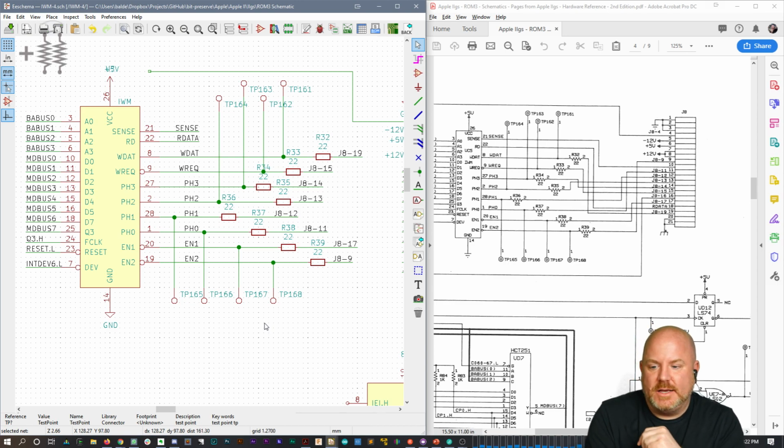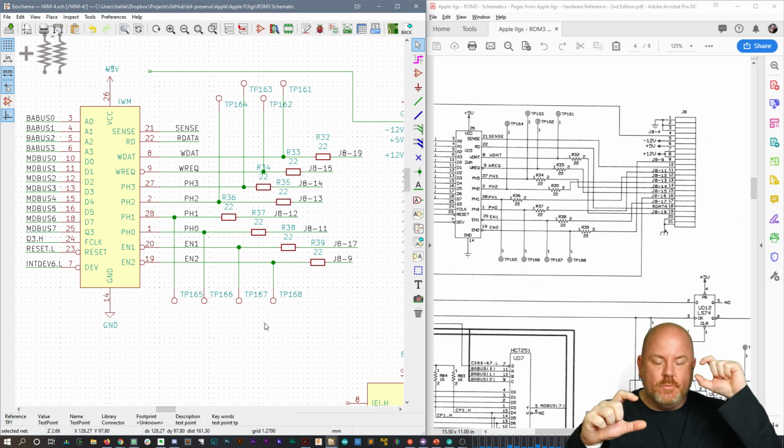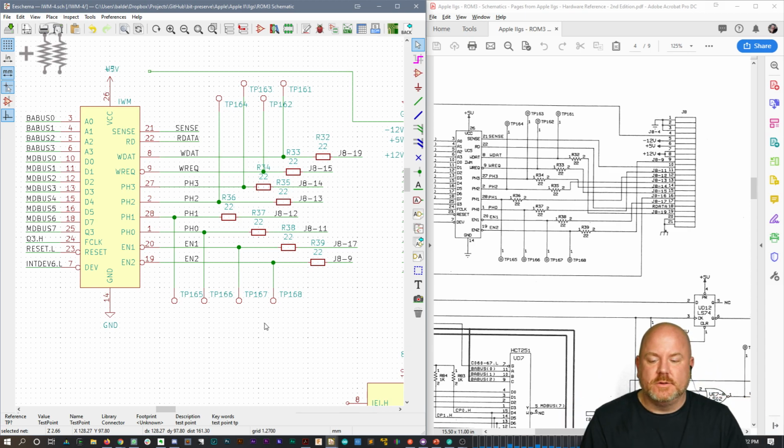What he didn't realize is his pull-up resistors were all at least 10K. And the input impedance of a multimeter is what? A megaohm? I think some might be 10 megaohms, but it's huge. The input resistance of this 6 gigahertz high bandwidth probe at DC was like 100K. So I did the math where I showed him what the voltage would be with a 10K and 100K resistor in parallel with each other. Not the most difficult math.